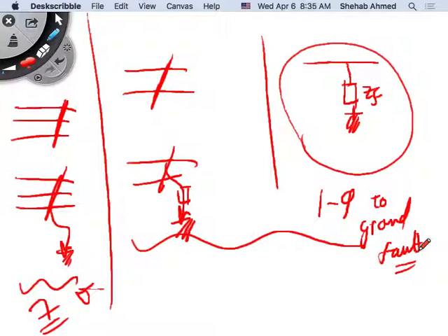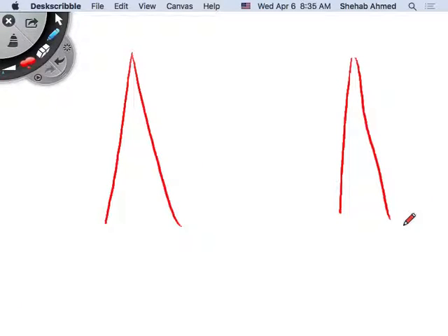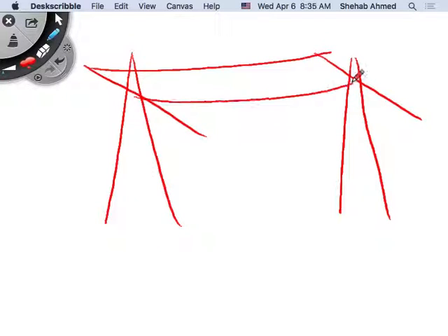This is the most common type of fault in a power system. Typically, do you think something like that would happen on the transmission lines? The probability of it happening on the transmission line is very slim. Because remember, at the transmission level, we don't even have the neutral wire passing through. We really have the 3 phases only, right?